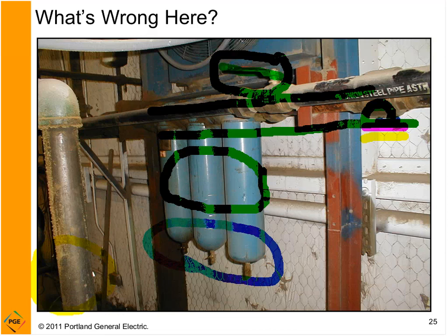And what I ask is, well, gee, if you're bypassing the filters, then why do you need all the filters? So you're obviously subjecting your system to dirty air. You've been getting along just fine, so what's up with that? Probably the solution here is to remove those filters, replace them with a nice, larger sized, adequate filter, even beyond adequate. But don't replace filters with filters that are too large. Filters actually can be too large, and then they don't do a good job at filtering, even though there's no pressure drop across them. So you must size them appropriately.